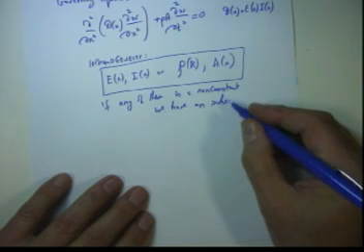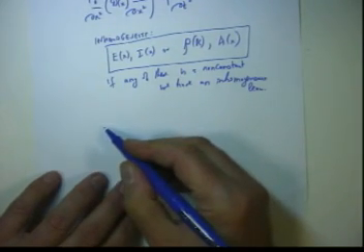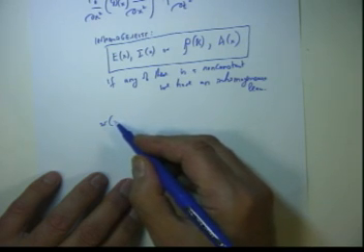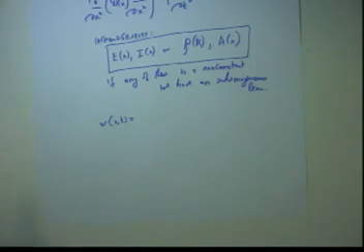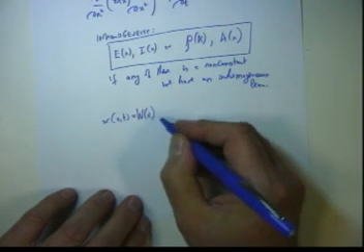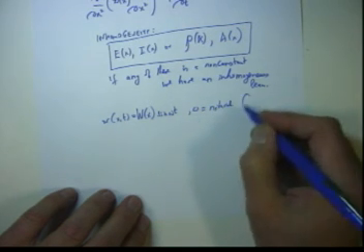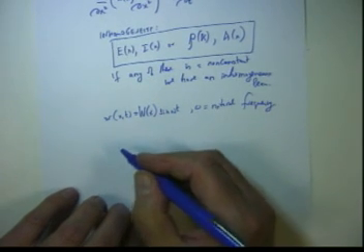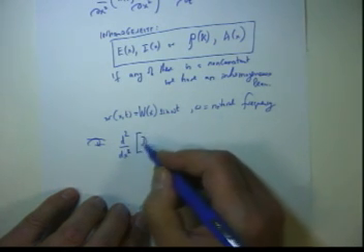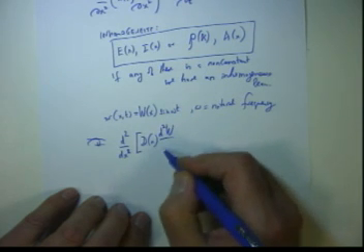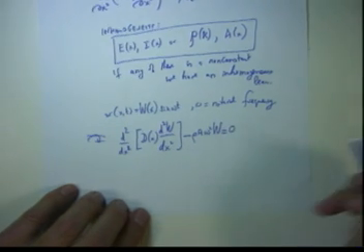We have an inhomogeneous beam. So, when we substitute w(x,t) equals capital W of x and then sine omega t, where omega is a natural frequency, we get the following: d2/dx2 of D(x) d2W/dx2 minus rho A omega squared W equals 0.